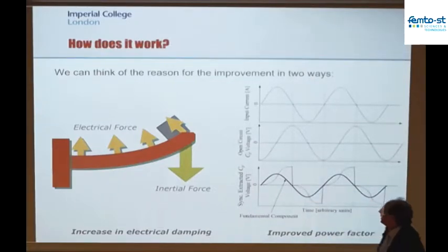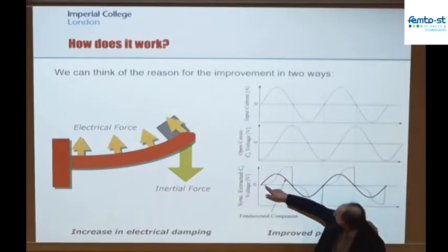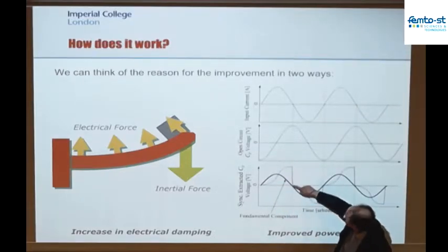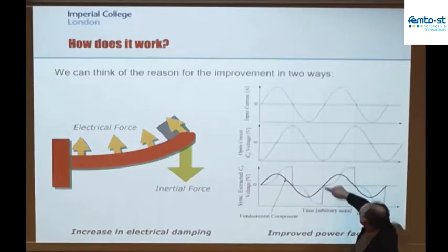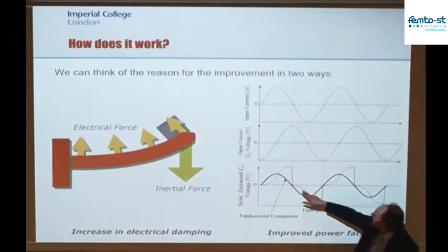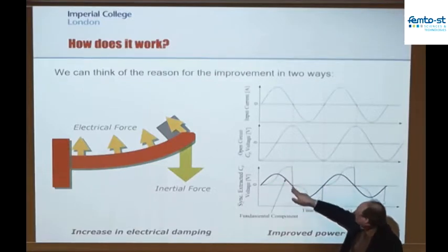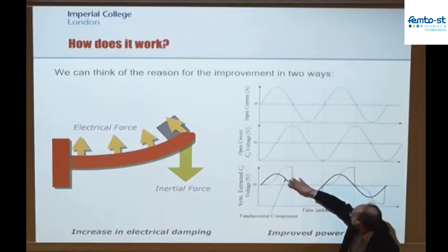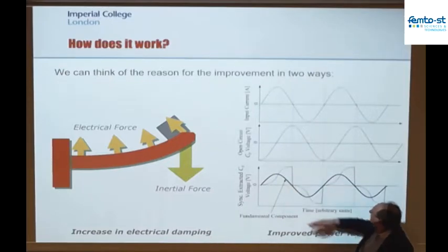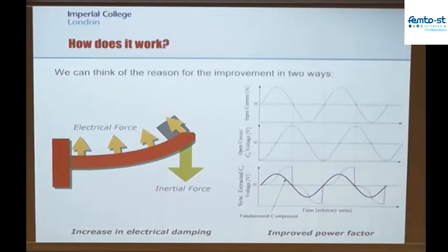This is what Michael and various others would call synchronous electric charge extraction. Then the voltage increases and gets pushed back to 0, increases and gets pushed back to 0. If you look at the fundamental component of this, so this clearly now has a bunch of harmonics present, but the fundamental component of this is now further shifted towards being in phase with the current.